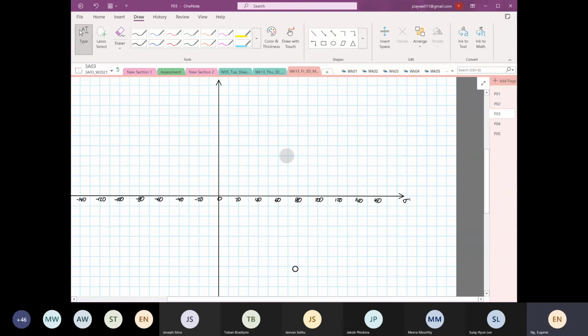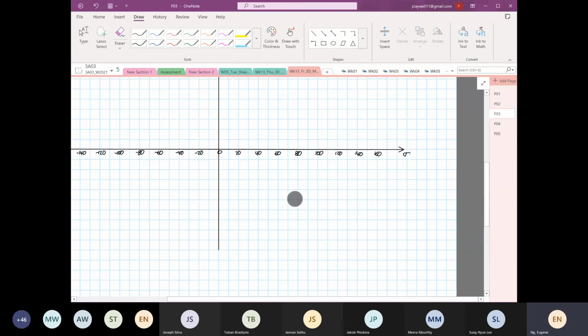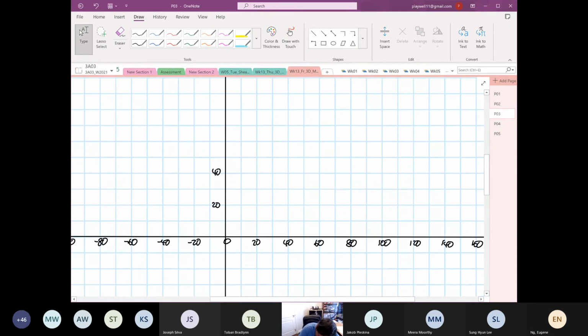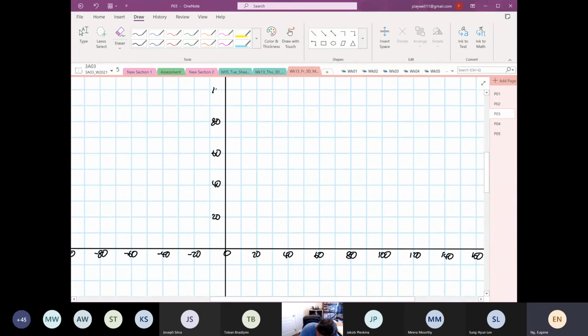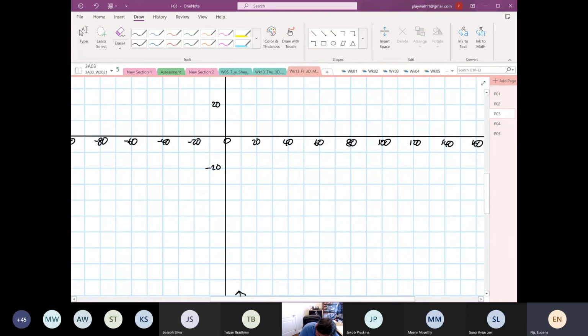Okay, so there's our shear. Clockwise, anti-clockwise, right? So 20, 40, 60, 80. I'm going to draw 100. Make sure the scales are the same in the x-axis and y-axis. Okay, if not, you don't get a Mohr circle. You get a Mohr oval.